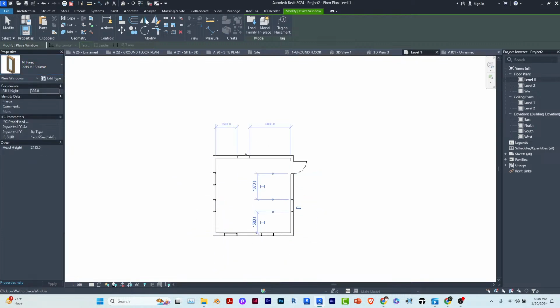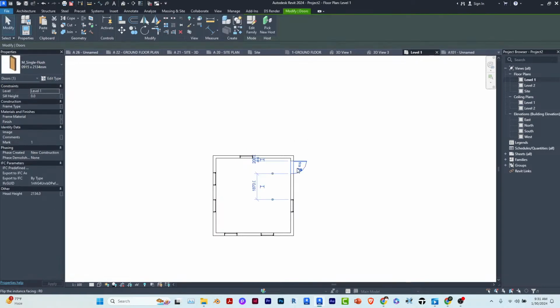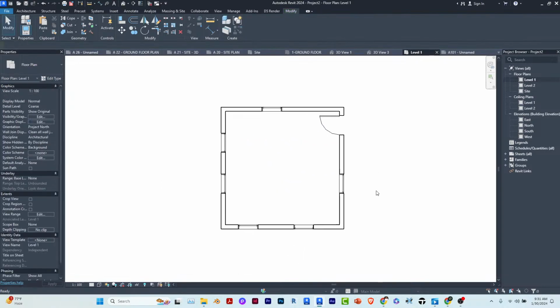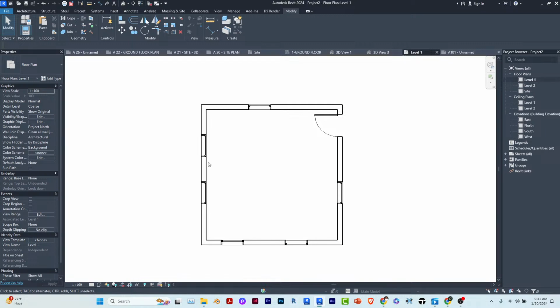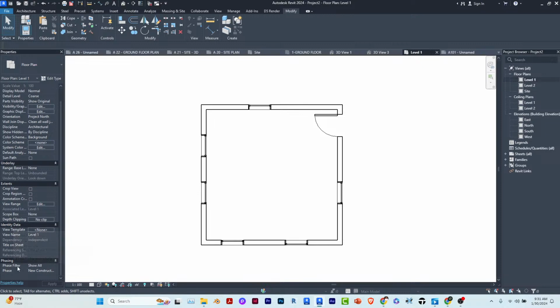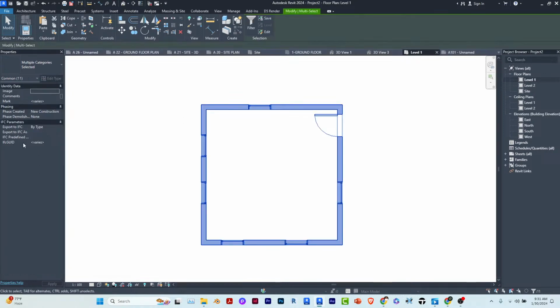So let's say you have this building this way, and you want to phase them. Now, whenever you are creating a set of buildings in Revit, if you scroll down here, you see phasing. It's always by default in new construction. If you look at it here, this set of buildings are in new construction. If the building you've now measured is existing, let's say you are doing a renovation, this is the existing drawing. You come under this phasing, you select everything you've done here.